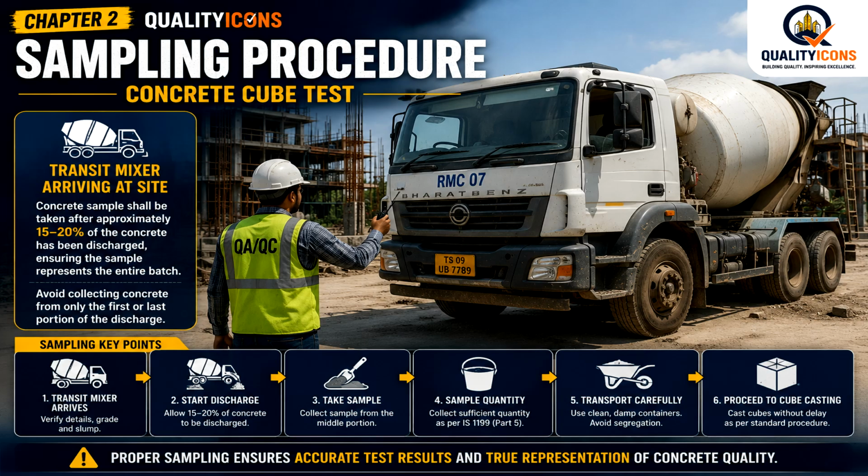Sampling key points. First, the transit mixer arrives. Second, start discharge. Third, take the sample. Fourth, sample quantity: collect sufficient quantity as per IS 1199 Part 5. Step five, transport carefully. Use clean damp containers and avoid segregation. Six, proceed to cube casting. Cast cubes without delay as per standard procedure. Proper sampling ensures accurate test results and true representation of concrete quality.